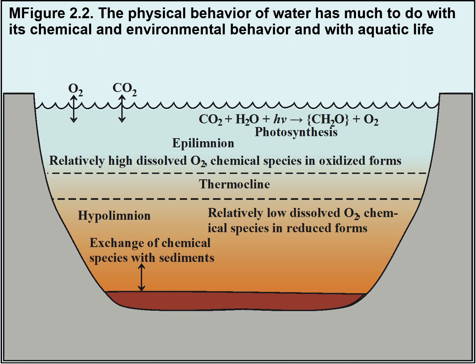We have 3 layers in most water systems if they're not turning over. The top layer of water, the epilimnion, epi means above, and lim refers to the surface waters like limnology, is actually separated from the lower layer, the hypolimnion. Again, remember hypo means below, like hypothermia or hypoxia. Those are separated by a thermocline, so a significant temperature gradient. That means the waters don't mix, and separate equilibria are going to govern the sediments.